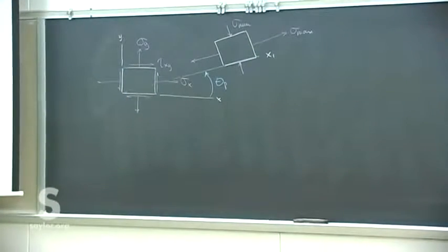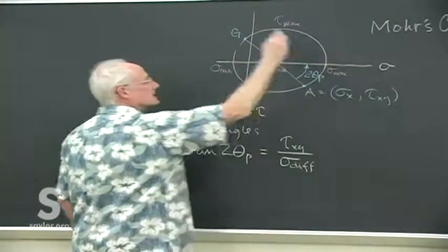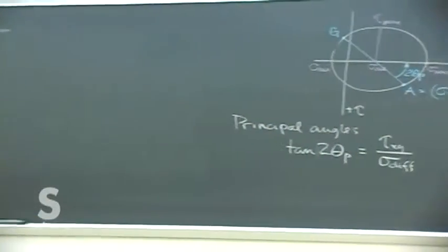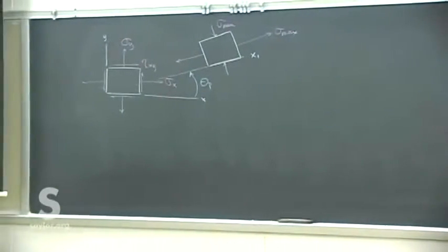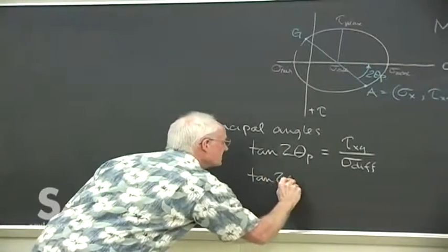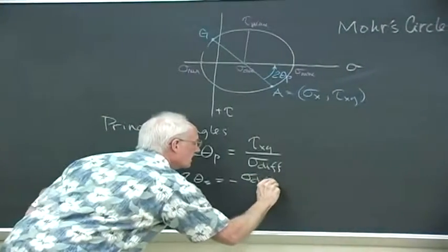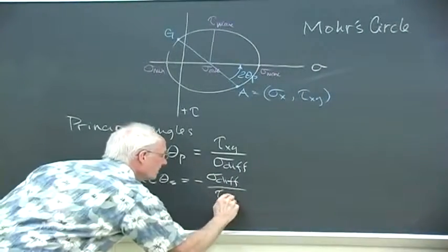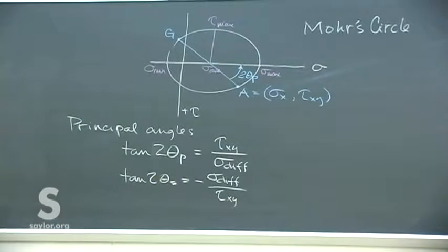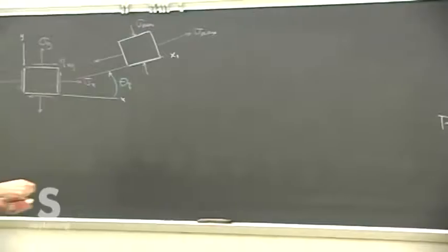And no shear stresses in that direction. Remember, that puts us at this operating point on the x-axis with no shear stress. There's also another angle called theta S, which, if you look at this carefully, do it a couple times, is just 45 degrees away from theta P, since it uses the same values just in inverse to each other.